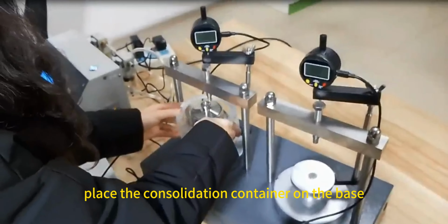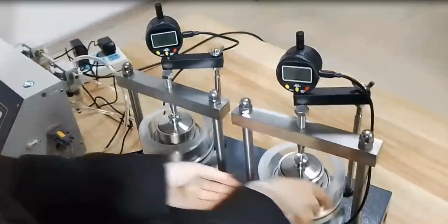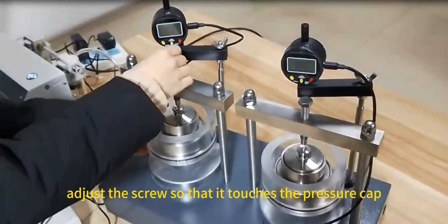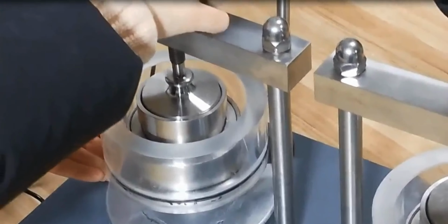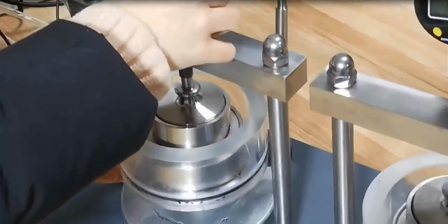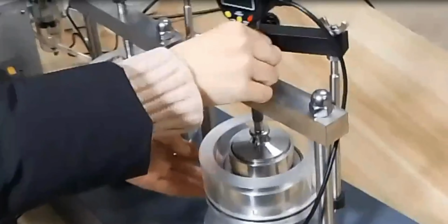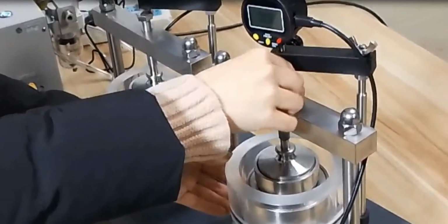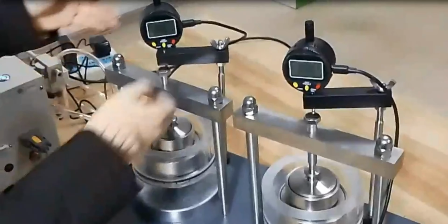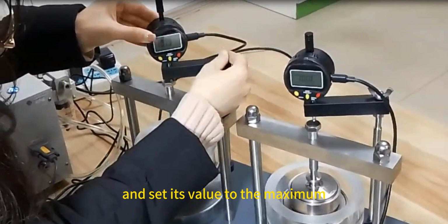Place the consolidation container on the base. Adjust the screw so that it touches the pressure cap. Put the digital display on the screw and set its value to the maximum.